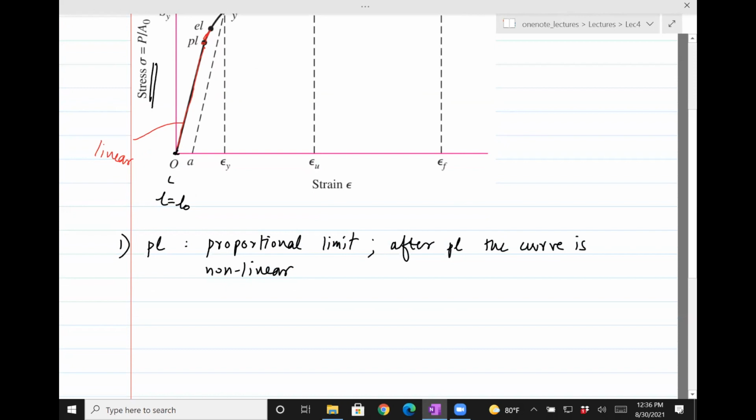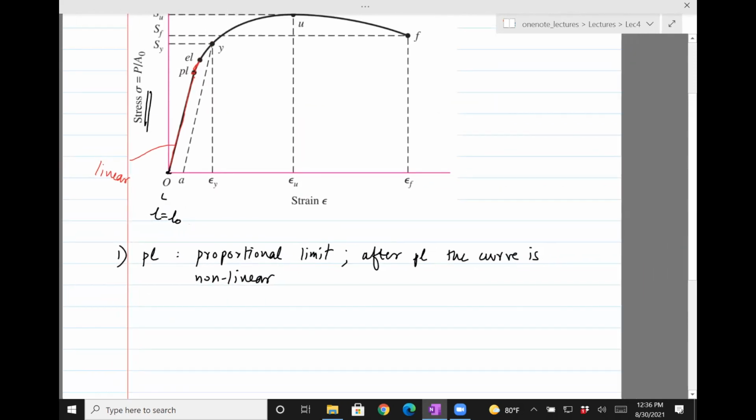If it's a straight line, then you can actually write an equation between stress and strain. So stress divided by strain is E, what is known as Young's modulus. Some people like to use Y for Young's modulus. That's the equation of a line, right? Y divided by X equals constant, and it passes through the origin.